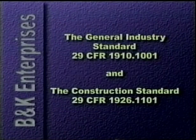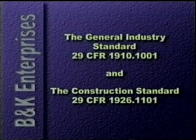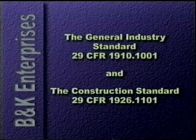The EPA issued a NESHAPS asbestos standard for renovation and demolition of industrial and commercial buildings. Also during this time, OSHA developed two regulations for asbestos exposure: a general industry standard, 29 CFR 1910.1001, and a construction standard, 29 CFR 1926.1101. These two regulations describe the permissible exposure limits to asbestos, proper work practices, and training requirements for all persons who may be working with or around asbestos-containing materials. A copy of each of these standards is included in your course packet.